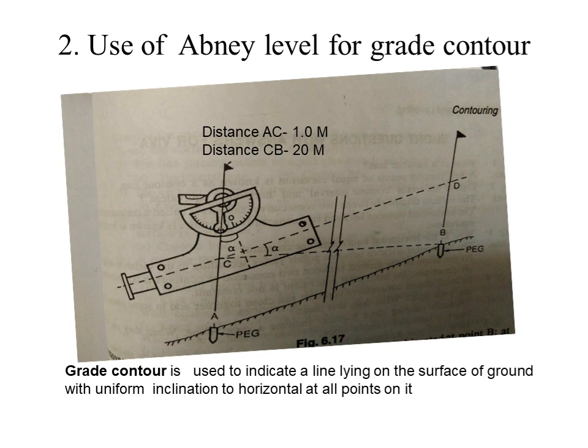Then we will consider case number 2, when the area is small and can be controlled from a single station. In this case, the method of radial lines is adopted to obtain the contour map. This is very slow and tedious but gives accurate contour lines.